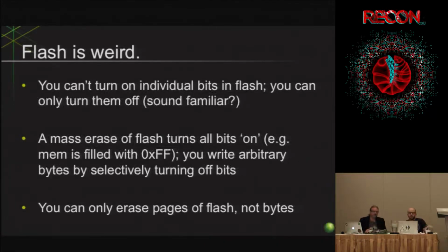But once you've got FF, you can start dropping 1 to 0 and at least create. If you have a blank slate, you can create anything. So the obvious case there is that if they're all FFs, then you can write anything there because you're just going to turn off selected bits. But if it's some other number, some other bit mask, then you can still turn off individual bits and create a different value. So you can still modify Flash in select cases. It's just not going to be general, and it'll be very situational on whether or not that is useful to you or not.